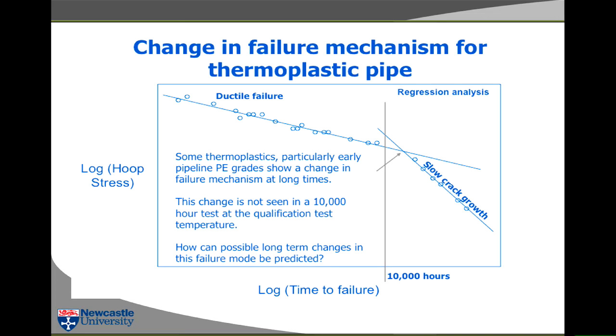You do, actually, what all plastics people do when they want to accelerate a result, when they want to get a result to happen earlier. And that is, they do tests at higher temperature. This temperature here is the design temperature, the qualification temperature. So your pipe is qualified to operate at the temperature where you obtain those results. You can't run at a higher temperature. But in the testing procedure, you can run at a higher temperature, and that accelerates everything.